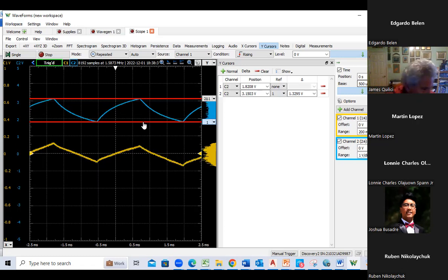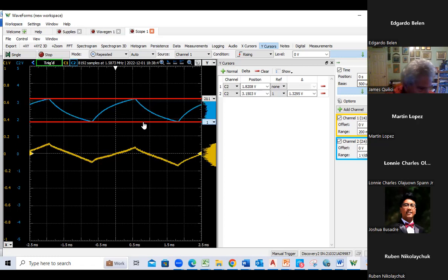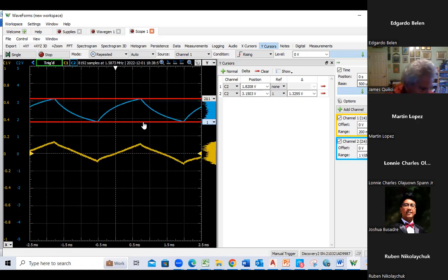Okay, it says present the final design in the form of a schematic diagram with all parts labeled, the one that you built. State the specifications for gain and output voltage swing along with the given specifications, and state the collector current and the value of VBB.